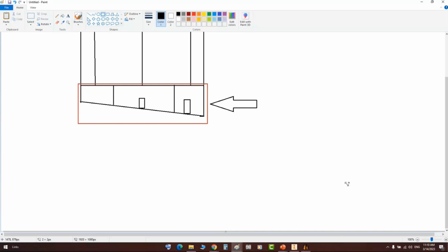Like if you have a skirt, you may need to define the imaginary part with the same information of the shell or the blade of the skirt, by defining the inside diameter and the thickness of the skirt. If you have a nozzle and a connection point at the end, you may need to define this imaginary part with the same information of the nozzle, like the pipe size and pipe schedule. So the concept between parent and child is completely different.